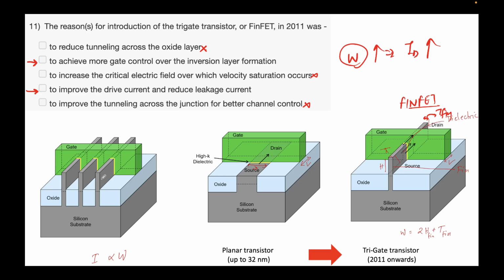Note, this is source. So source and source, and on the other side you have drain. You can short them electrically and apply VDD over here, and also you can short them like here and ground them, let's say. This oxide is for insulation purposes. This is not the gate oxide. The gate oxide is denoted by this yellow, the gate dielectric, that is.